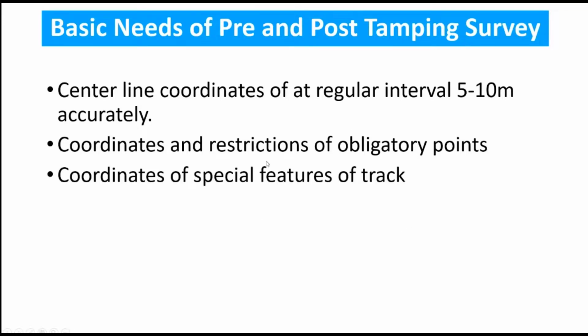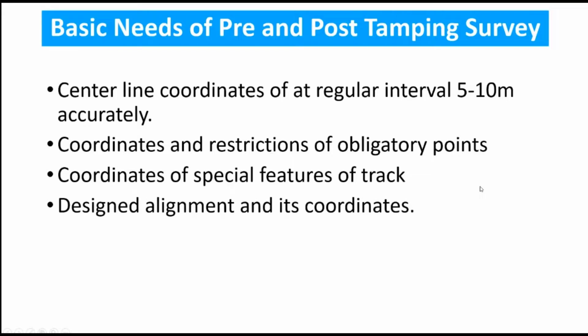Then also the special features like gradient, start of curve, end of curve, and where the vertical curves are, they also have to be picked up. Then super elevation, degree of curve, everything has to be picked up during the survey. Then we determine the design alignment.